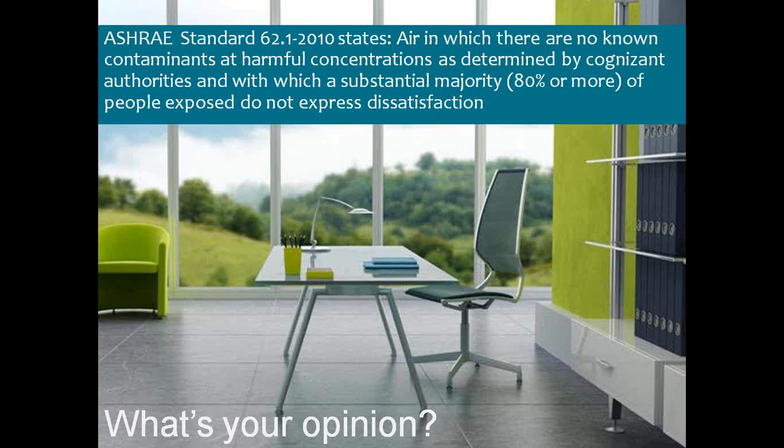As we start out our discussion today, what we know is that indoor air quality, believe it or not, has an official definition of what acceptable indoor air quality is. ASHRAE, which is the American Society for Heating, Refrigeration, and Air Conditioning Engineers, has given us a definition which is really quite interesting. It says there, air in which there are no known contaminants at harmful concentrations as determined by cognizant authorities and with which a substantial majority, which is 80%, do not express dissatisfaction. So this is a really prime example of the 80-20 rule at play.